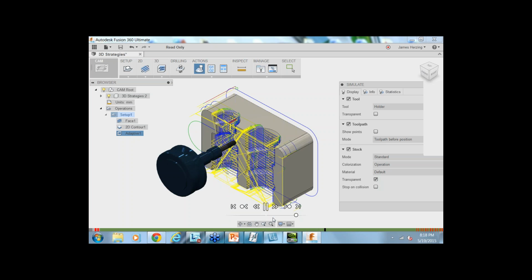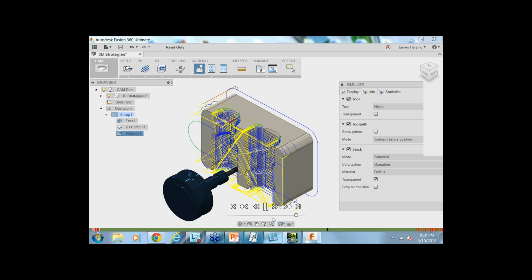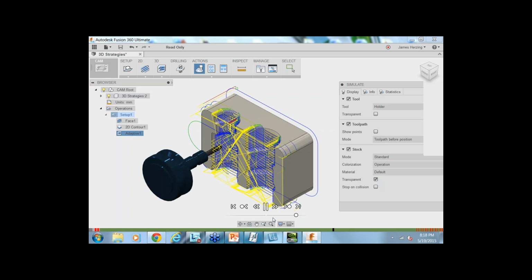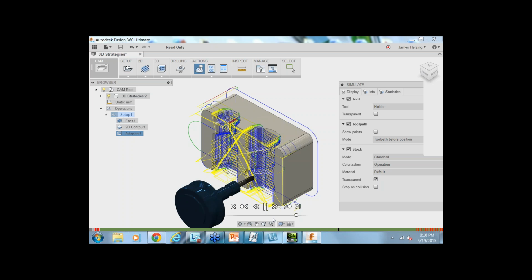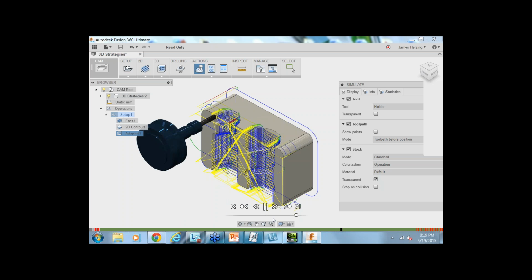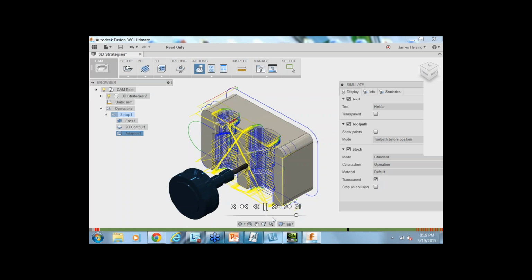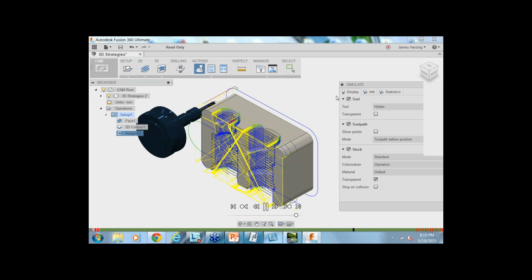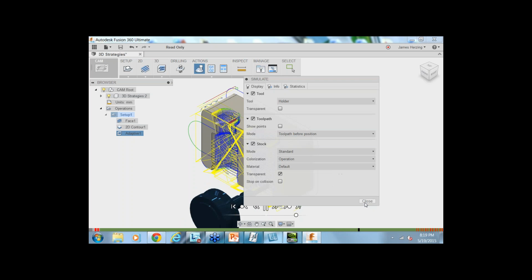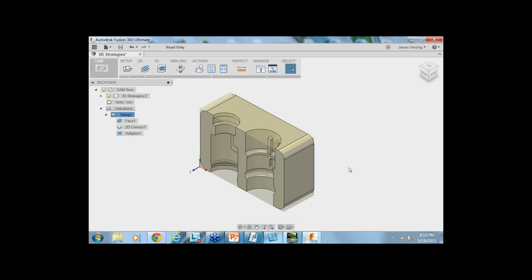Use 20,000 millimeters per minute. Those are not anywhere near real life figures unless you're running some of the new Mazak tri-axis machines. Typically on a Tormach, for the size of this component, you'd probably be running about an hour, hour and a quarter for that